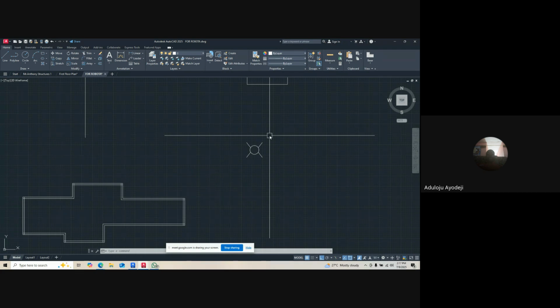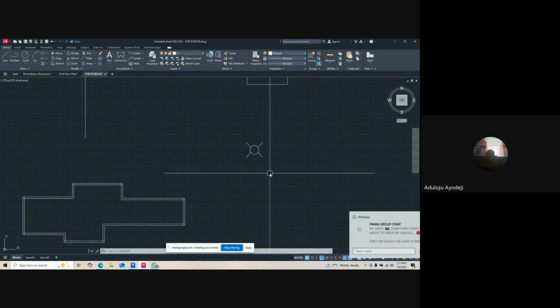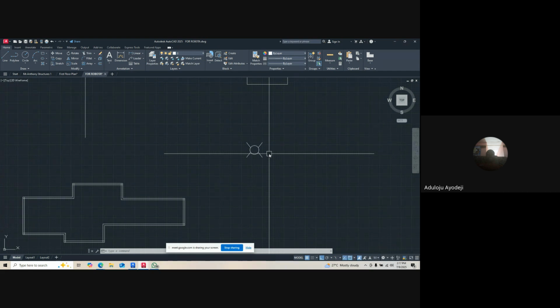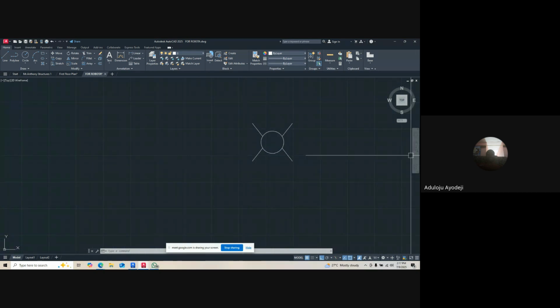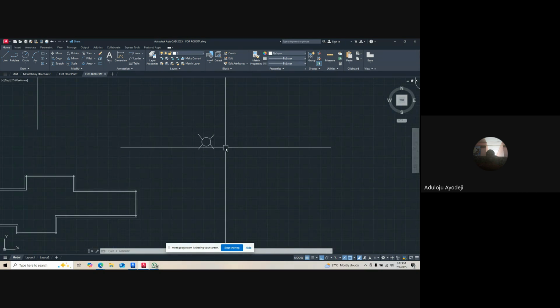In this AutoCAD interface, I'm working in millimeters. We have inches, feet, centimeters, but my interface is set to millimeters. I showed you how I created this interface through my dimension style, DIMSTYLE. I believe you can still record. So if I want to scale this now, first thing you do, are you all listening to me?